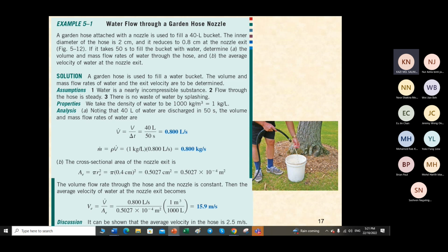When the duct reduces in dimension, the duct loss increases and the velocity also increases. We cannot have unlimited velocity, because I have to control the velocity at which air is discharged in the heating, ventilation, and air conditioning system. If the velocity is too high, people will feel uncomfortable.